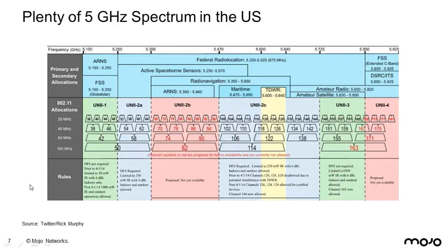1, 2, 3, 4, 5, 6 80 megahertz channels, 2 non-DFS and 4 that are DFS. And so I'm recommending going with 80 megahertz because that's how you get your most bang for your buck when you go from 11n to 11ac, by doubling the channel width. And a lot of folks have already done that. They've gone with 80 megahertz. So if you need the extra capacity, we recommend that. The solution we're going to talk about today for the classroom is with 80 megahertz.